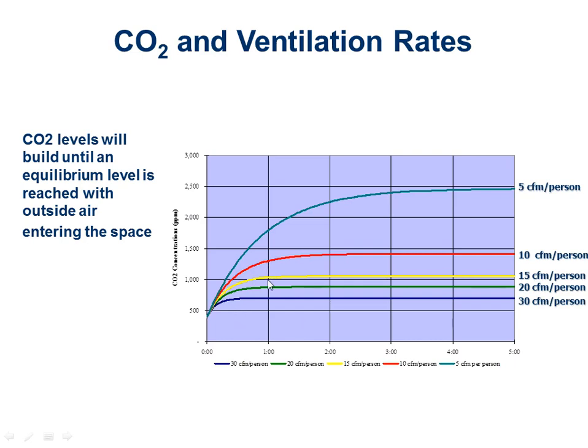If I'm bringing in, what did we say before, 17 CFM per person is a common building, it's about a half an hour or so before I get to a reasonably level line here. And then I'll be reacting to that. So it doesn't take very long at all. I know a half an hour sounds like a long time, but in the thermodynamics of an entire building, it's not very much time at all. And most ventilation standards do allow you as much as 2 hours of non-ventilated time if you want, although there's no reason to do that, but you could theoretically do it. So getting there in a half an hour is plenty of time.